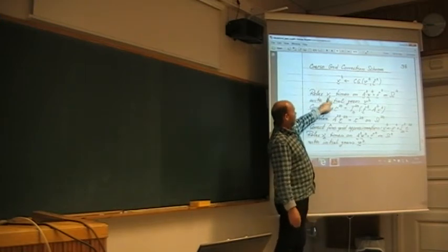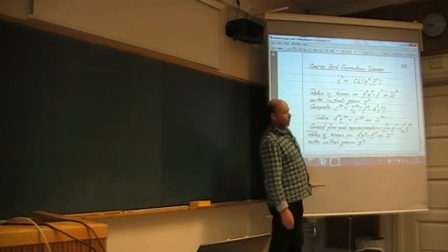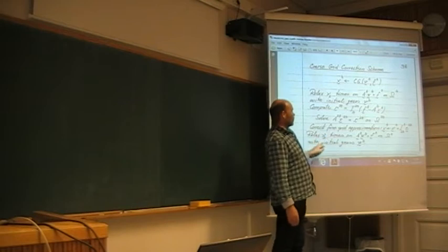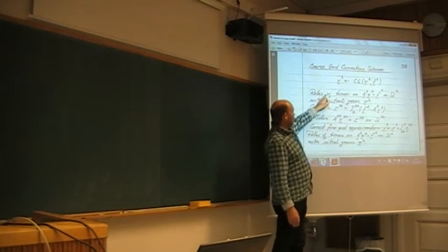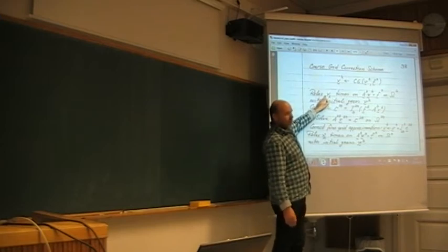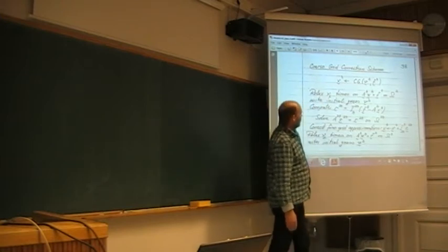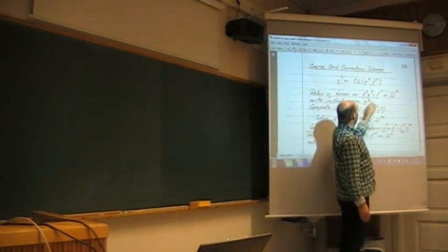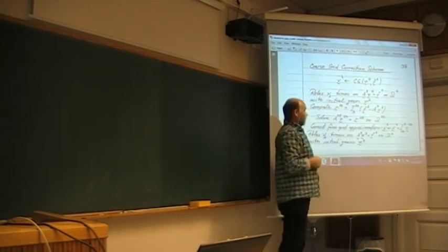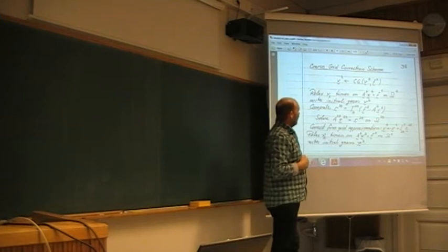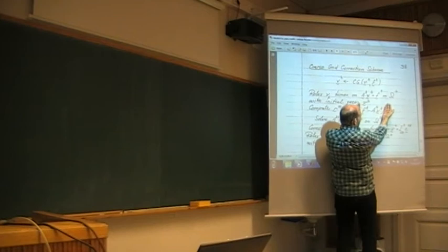Nu 1 is the number of iterations on the level when we are going downwards to coarser and coarser meshes. Nu 2 is the number of iterations when we go up again. So they can be different numbers. Normally they are quite small, 1 or 2, 3 maybe, not more. That's enough, but you can play around with them. Anyway, we start here, we iterate on this one to find some numerical value on the fine mesh, which of course is wrong. Then we calculate the residual. This is the residual on the fine mesh.